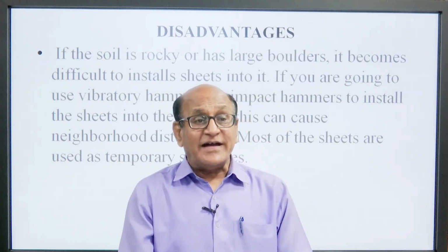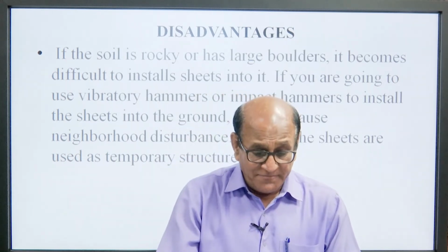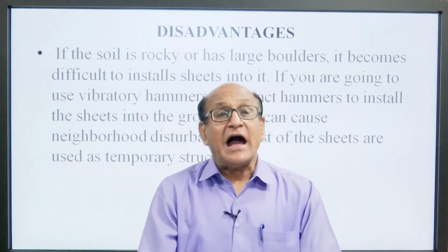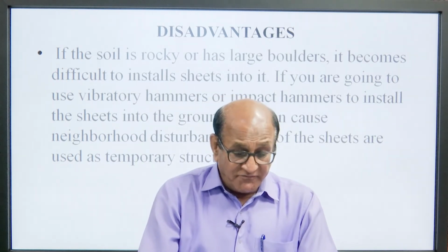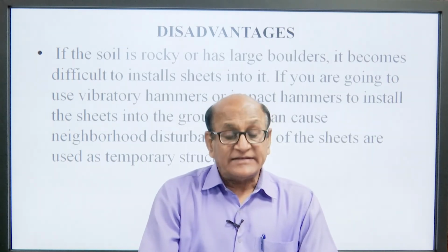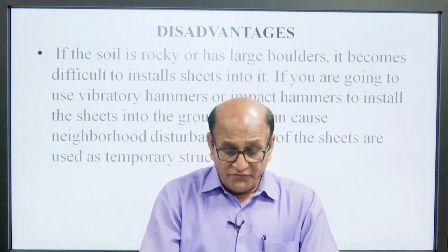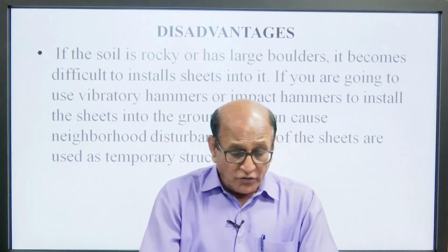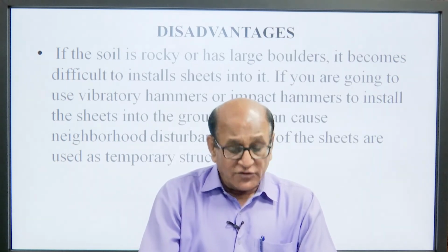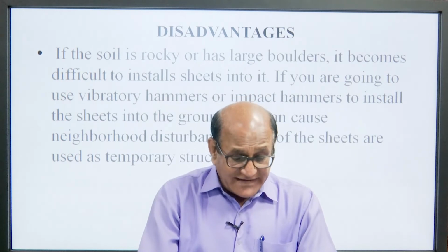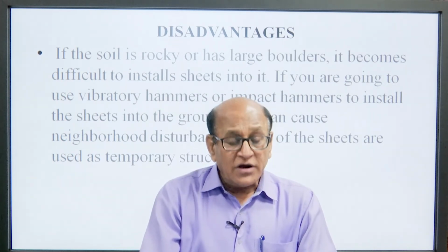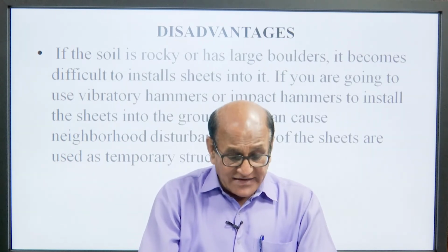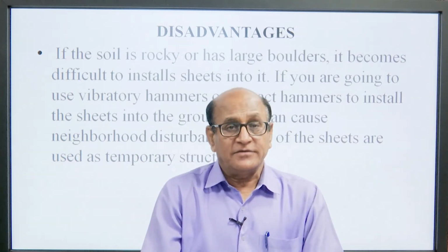Now, the disadvantages of sheet piles: if the soil is rocky or has a large boulder, it becomes difficult to install a sheet pile into it. If you use a vibratory hammer or impact hammer to install the sheet into the ground, this can cause neighborhood disturbance. Most sheet piles are used as a temporary structure.